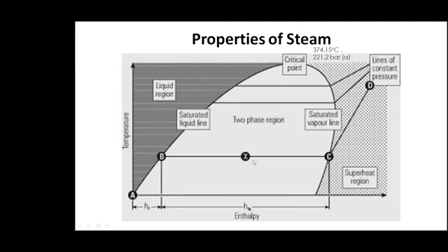So 1 kg of steam can transfer almost 540 kilocalories here at this point. Whereas if we go for 30 bar steam, 1 kg of steam will transfer only about 490 kilocalories. So there is a reduction in the latent heat that is going to be available. If you keep on going up with pressure, at one point the latent heat becomes zero, and that point is called the critical point. It occurs at 374 degrees and 221 bar, where the latent heat becomes zero.